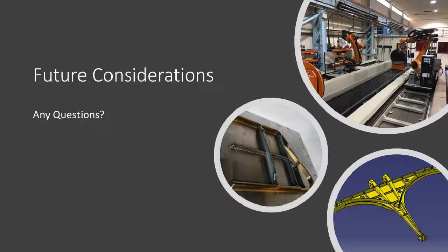each and every time. I could certainly ask the question if they've had any further examples of issues with some of the stuff they've printed, but I would have to forward that information on. We did, some years ago, design some covers using FDM for some avionics equipment. And we noticed brittleness was the biggest problem with them, but obviously we would use material and construction processes appropriate to the application, so we would never use anything with anisotropic weaknesses in any sort of critical application.